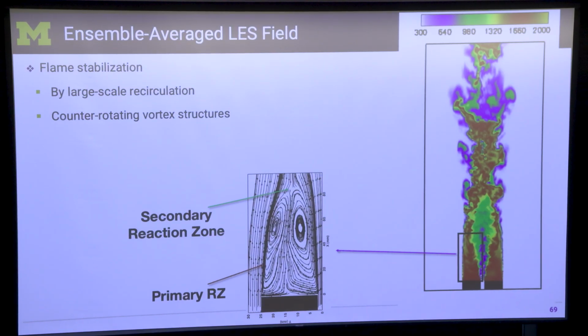So they can change operating, the flame shapes can change. Flames can sit higher up or lower down for the same operating conditions sometimes. They can move back and forth. So those kinds of problems where nominally the boundary conditions are stationary in time, but the flow features are unsteady or they're exhibiting limit cycle behavior or different steady points, attractor points, for those kinds of problems, LES is very useful.